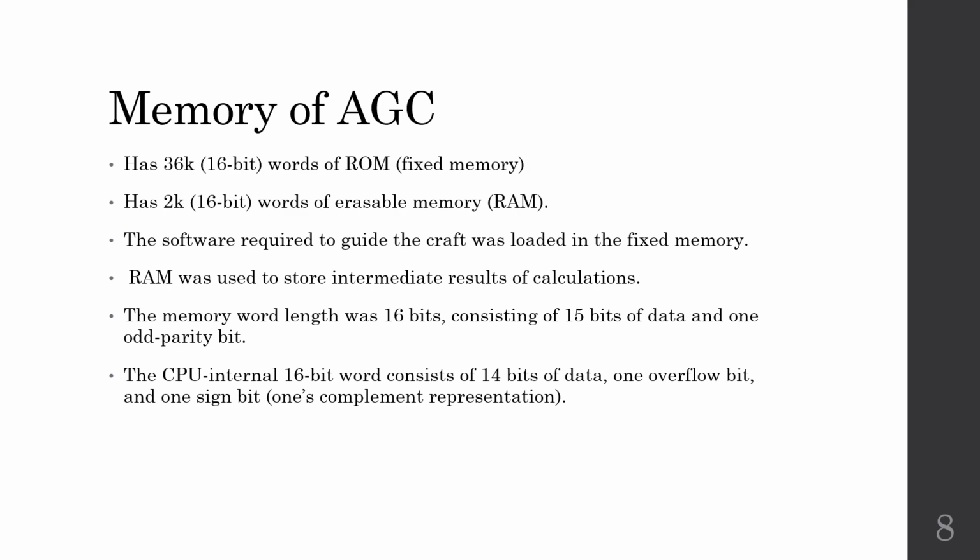memory word in the CPU internal is also a 16-bit word, but 14 of the 16 bits are allocated to data, 1 bit is a sign bit and the other is the overflow bit.